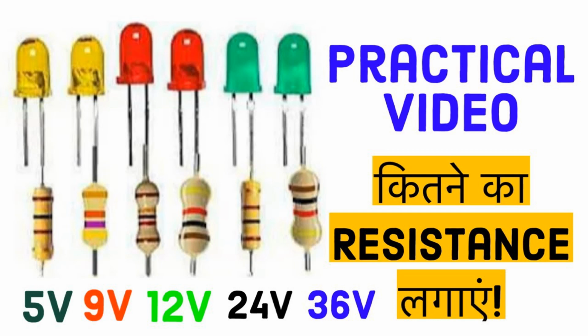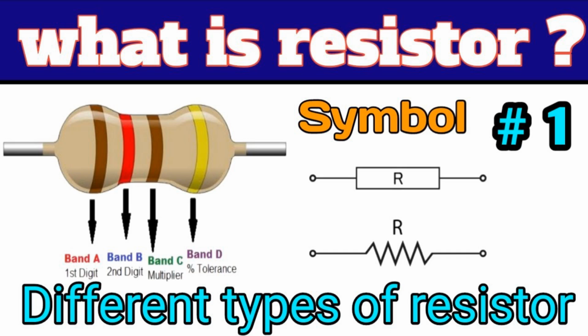Using the voltage divider formula, Vout equals 12V times 5k ohm over 7k ohm plus 5k ohm, which equals 12V times 5/12, which is 5V. The output voltage, Vout, is approximately 5V as desired.